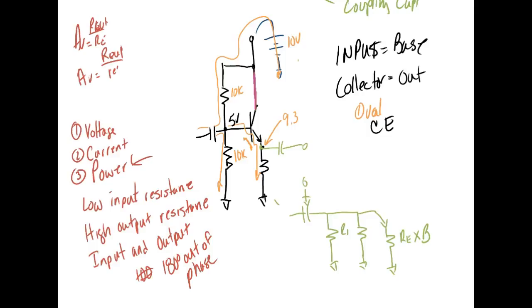Okay? Y'all understand? What would I have right here? I'd have 4.3. Okay, the transistor, is it on or off? Is it active? Well, right here I have 10. Right here I have 4.3. Voltage collector to emitter would be equal to what? 5.7 volts. Is it active? Saturated? It's active. So what's going to happen if I bring in 1 volt peak to peak?